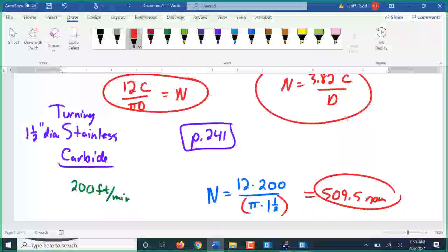For aluminum, all the speeds on here are assuming you have pressurized lubrication. There are two schools of thought with cutting aluminum. One is you cut it slow so it doesn't melt and gum up your tools. The problem with that is you get more surface tears in it. The other theory is you go high speeds and you just blast it with coolant to keep the tool clean.